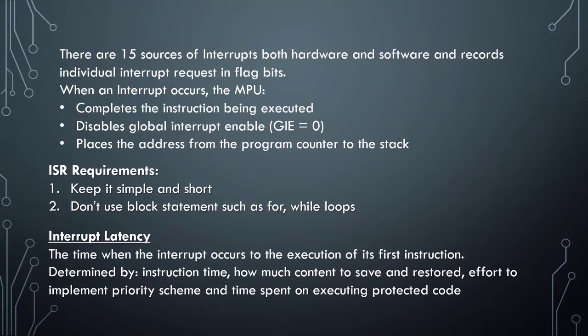What are some of the ISR requirements? Among the requirements is that the service routine needs to be kept simple and short. Also, for the interrupt to work efficiently, we should not use blocking statements, such as the for and the while loops.